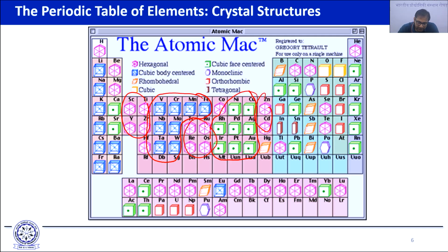So as you are finding two well-separated regions of the periodic table where the crystal structure is changing, this starts telling you that here you have a certain number of valence electrons, and over here you have a different number of valence electrons, and therefore the concentration of the valence electrons that you've got is going to affect which type of crystal structure forms.